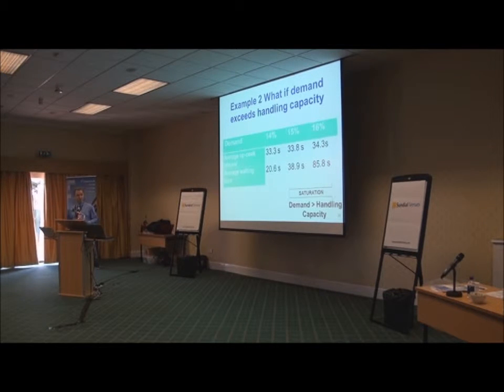So the waiting time goes up, and you can see we've got the waiting time, so that the interval stays around the same, in fact. The system's still working fine. System interval, lifts dispatching regularly, 30 seconds. There happened to be a big queue at the lobby, so the interval stays about the same, but the waiting time goes up.